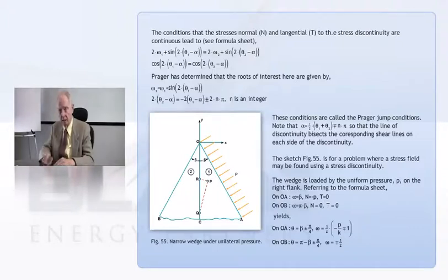That's the first thing we talked about with an orthogonal grid on each side. But because of the way things are, they've got to be, these stress fields have to be tilted. And when they're tilted, then where they go together, you've got to satisfy the jump condition.